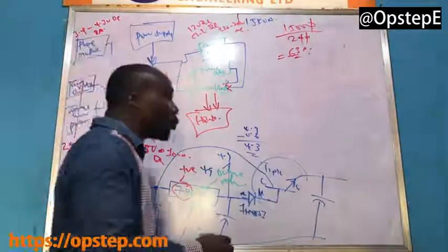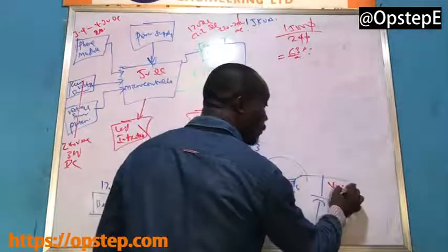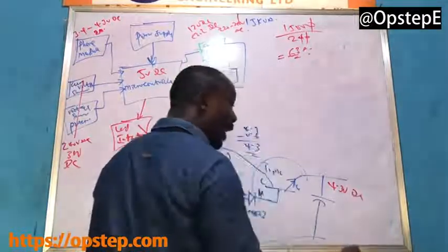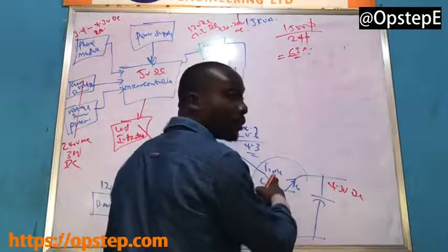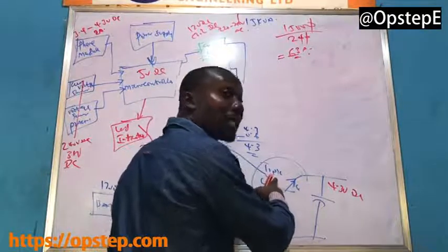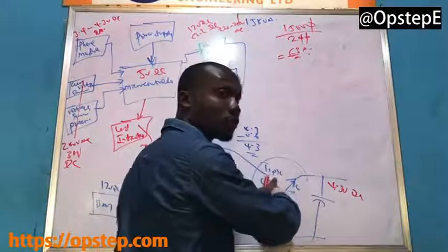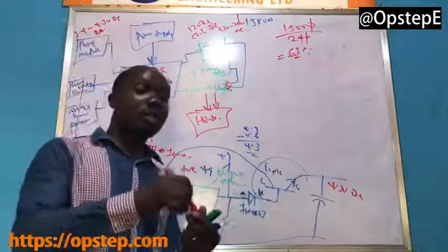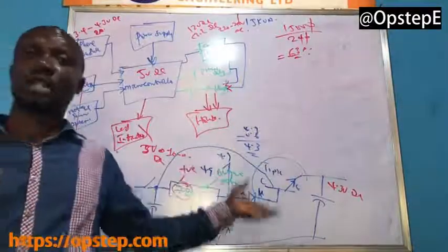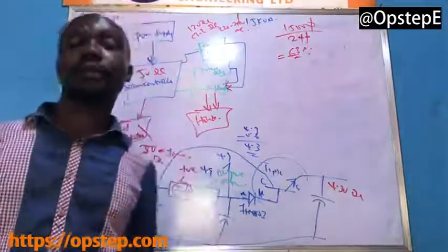So that at your output, you now have 4.3 volts DC at the current allowable by this transistor, many times higher than 5 amps, sometimes as high as 10 amps, depending on the choice of transistor. Again, for us to determine at what current the transistor is giving this, we need to discuss the hFE of this transistor and how gain is calculated.